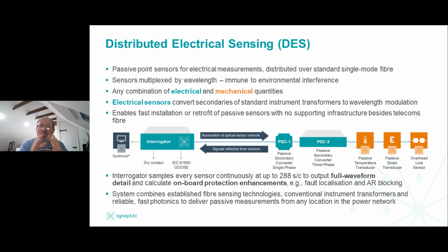That's why we get used for a whole combination of applications where this is actually a protection class system. Normally what we're doing is looking for faults in complex circuits and either tripping or helping the protection scheme to locate the faults in section and provide a more granular and targeted post-event response to a fault. But when we're not clearing faults very rapidly, which is a great feature of this technology, we're permanently synchronously monitoring all these locations, looking for interesting correlations that would give an early warning sign of a problem.